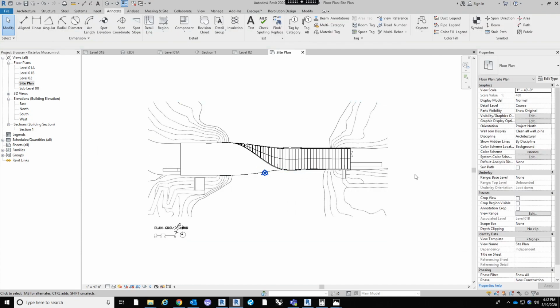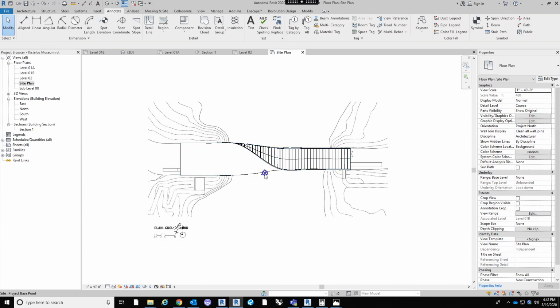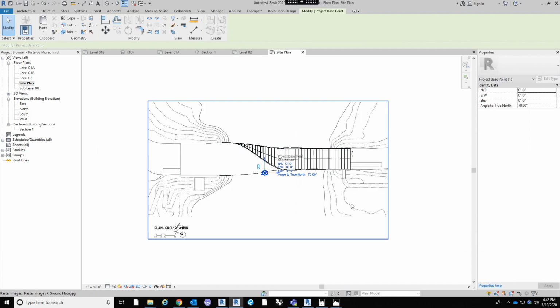If you draw to true north at a weird angle, it's just going to make setting up your drawings and views that much more difficult, because then you're going to have to angle and rotate every one. It's going to screw up a bunch of stuff. So once again, draw it orthogonally, draw it completely 90 degrees, and then rotate by typing it in here.